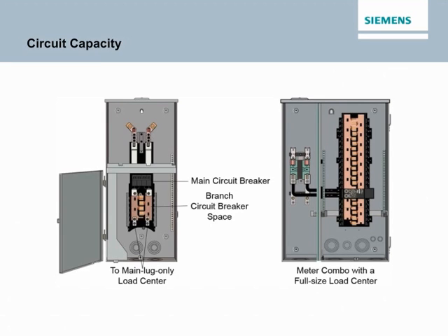Each meter load center combination has a circuit capacity. For Siemens meter load center combinations, the most common circuit capacity is 8 1-inch spaces and 16 possible circuits. For example, the MC0816B115CT meter load center combination shown on the left in the accompanying illustration provides a main circuit breaker and space for additional outdoor circuits, such as for an air conditioner or well pump.